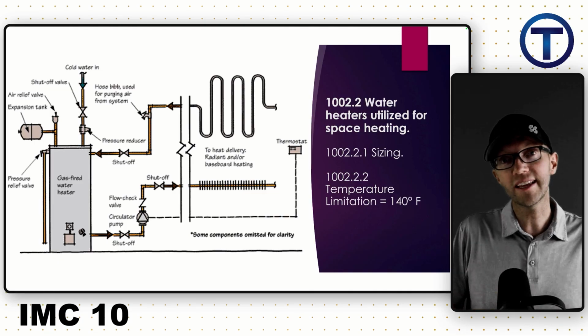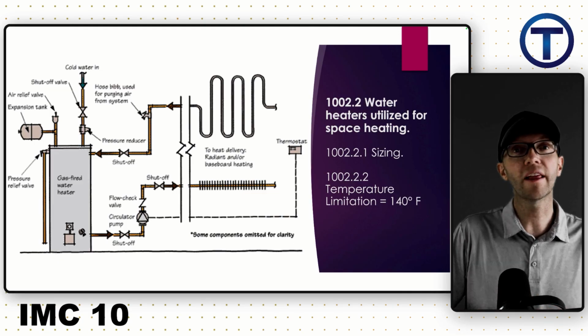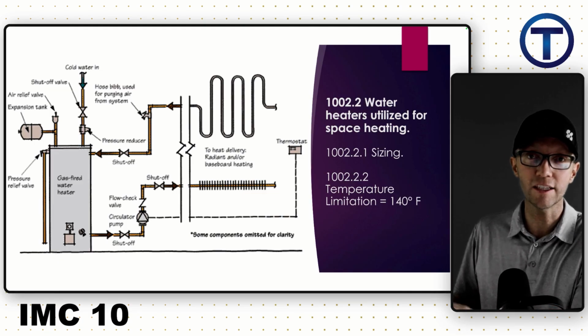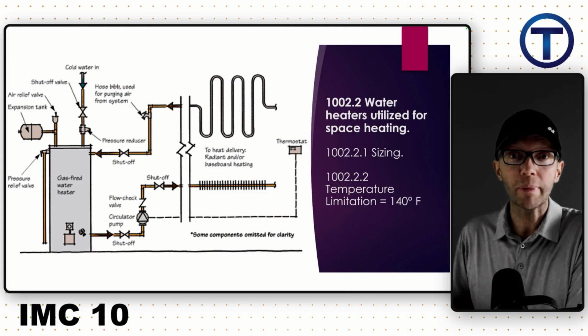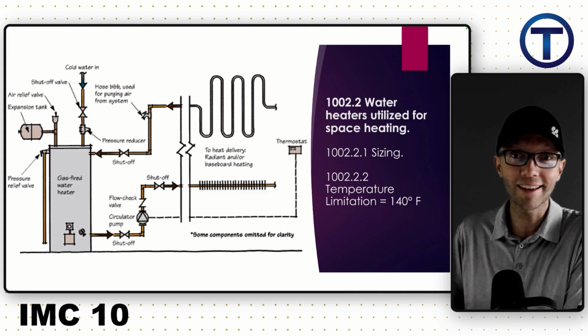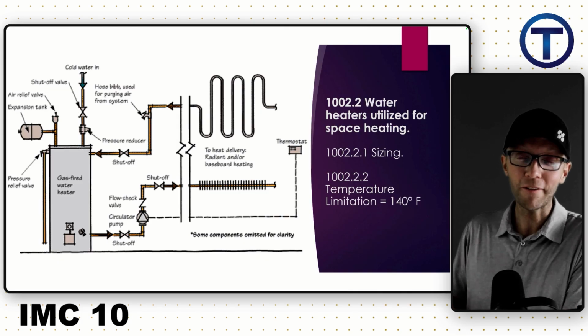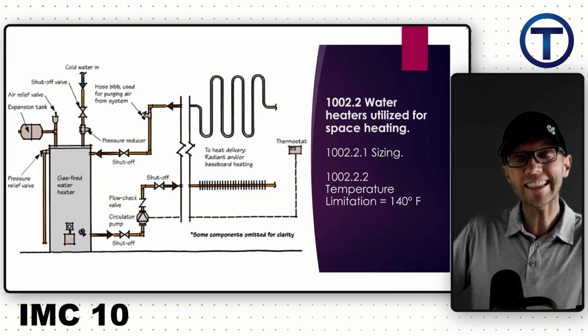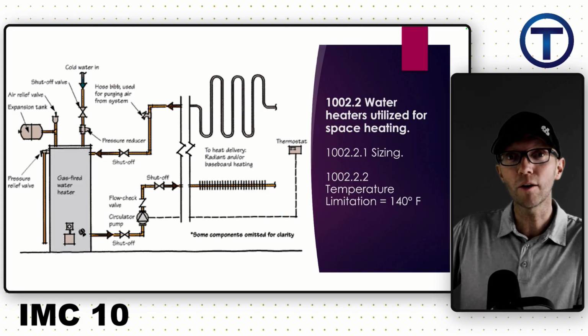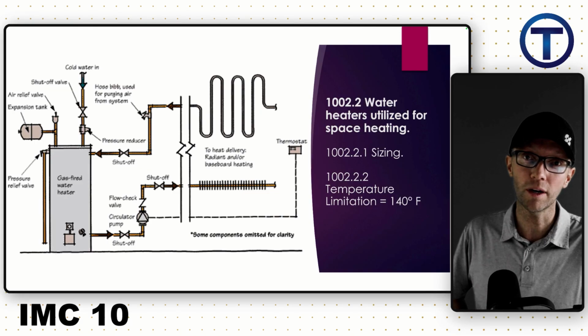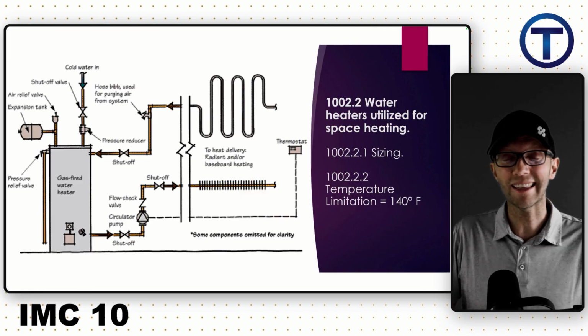If you take a standard tank-type water heater and throw it into a space heating situation, it doesn't have enough BTUs. That's the truth. You can get that 40 or 50-gallon tank with a 60,000 BTU rather than a 40,000 BTU when you're heating space, and that's what you need.